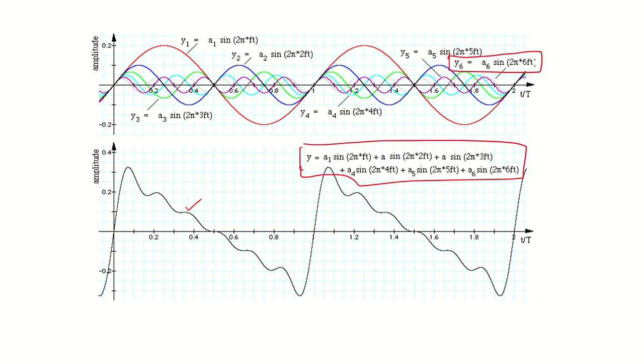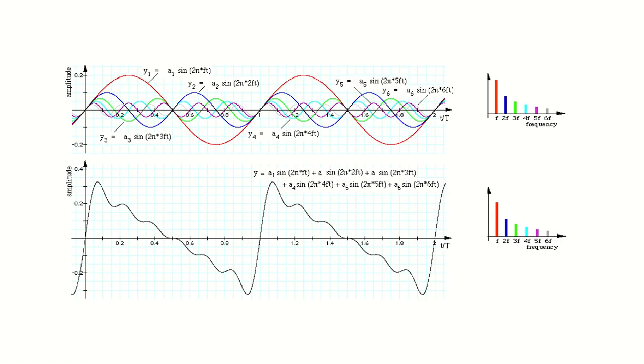So the Fourier transform helps to figure out which frequency component is creating trouble, which is exactly the noise signal, and we can filter out that signal. If we convert these different frequency components using the Fourier transform, this is the resultant Fourier transform of these 6 different frequencies.